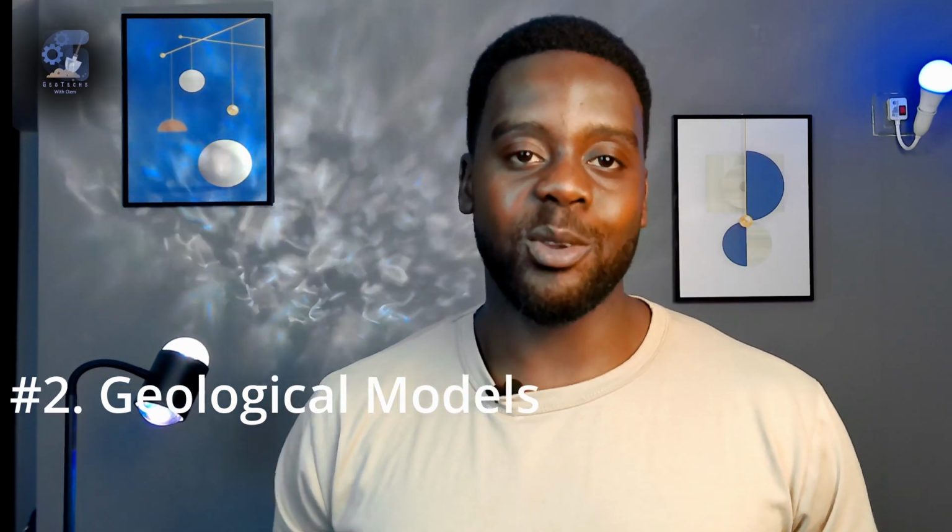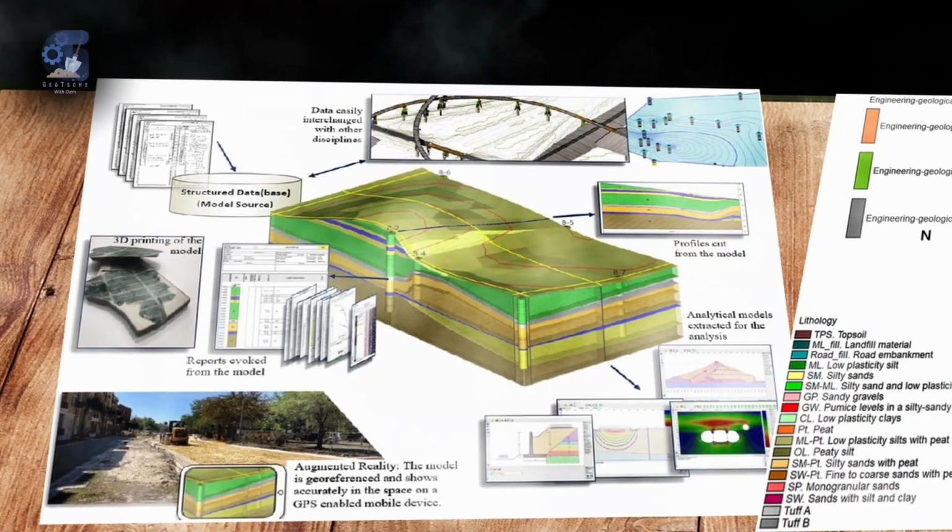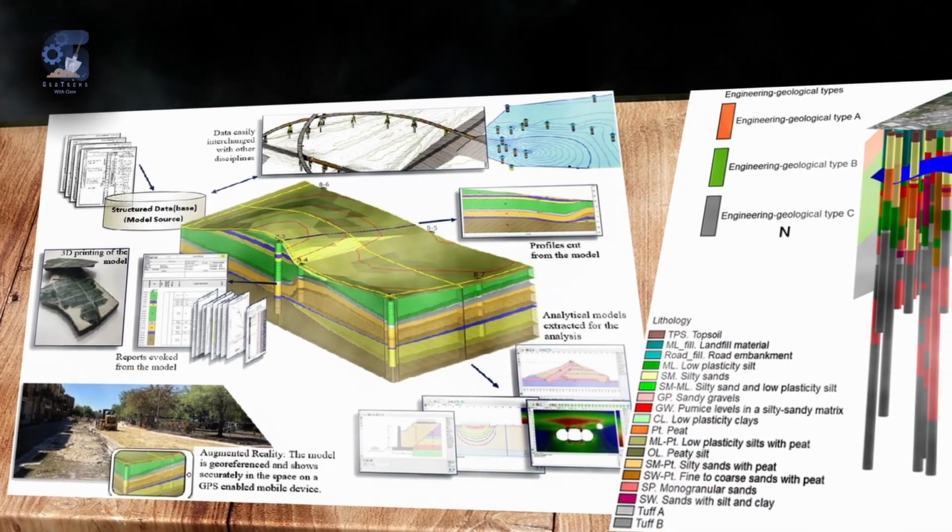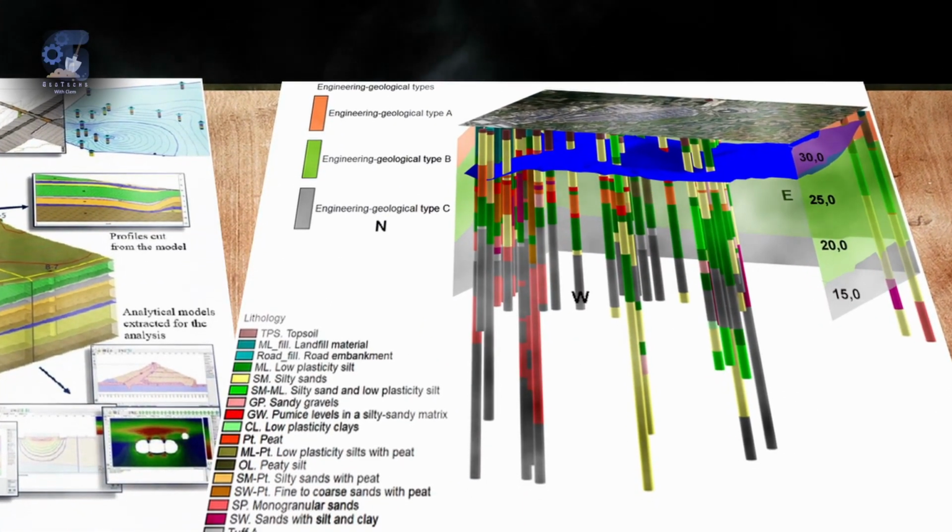Remember, the foundation doesn't work in isolation. It interacts with the superstructure and the surrounding soil. So, analyzing these interactions is essential for an economical design, especially in complex projects. Now, based on the mixture of the geological and geotechnical information collected during the desk studies and the ground investigations, appropriate geological models of the site are generated, which are an essential requirement for safe foundation design. They serve as a 2D or a 3D representation of the soil and rock layers and their properties.